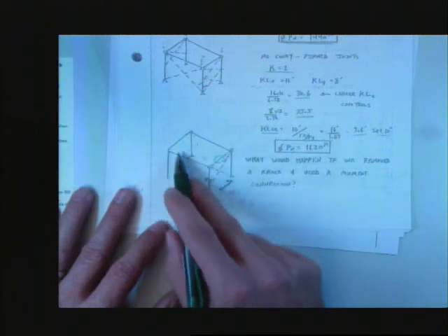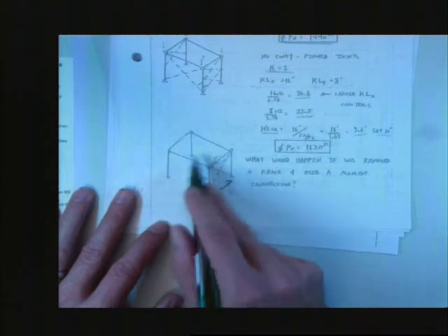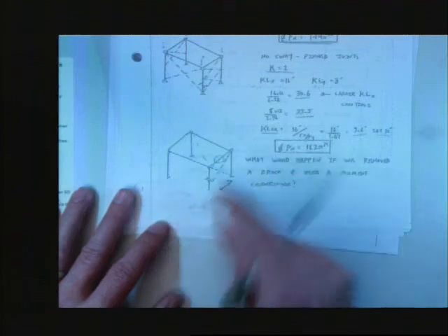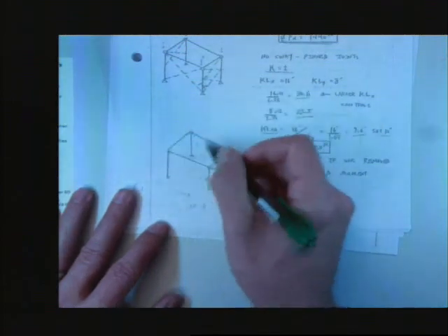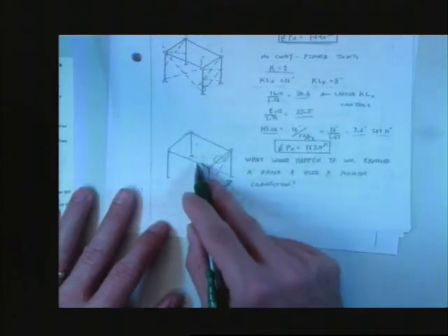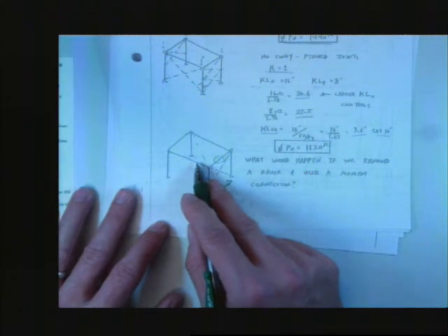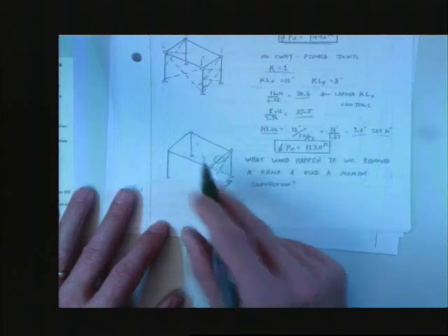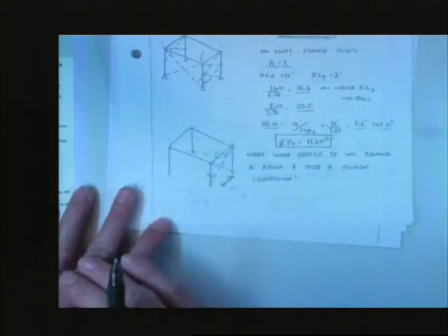This could not work under a flexible diaphragm. The back frame has a pin system. It's going to try to fall over. It's going to ask for help. If the diaphragm's not strong enough or stiff enough to transfer the shear to ask for help, it'll fall right over. Does that make sense?